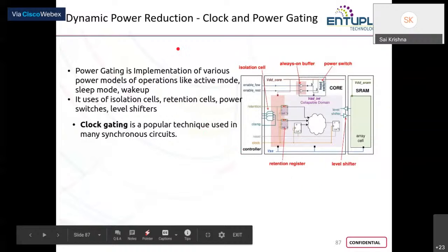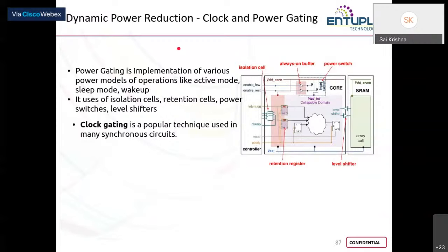So when you perform IR drop analysis, it is not only about your power mesh or your connections, the routed connections. You also, I mean, there are a certain special set of cells that are induced particularly to check this, to keep a check on your power usage. So that is where your concept of single domain power analysis or multiple domain power analysis comes into picture.